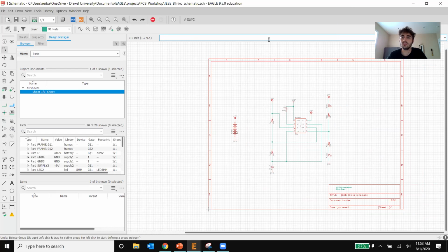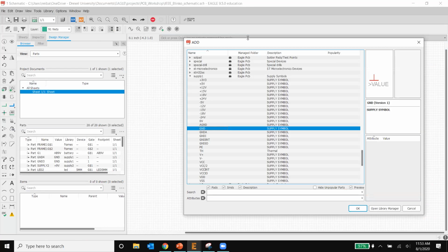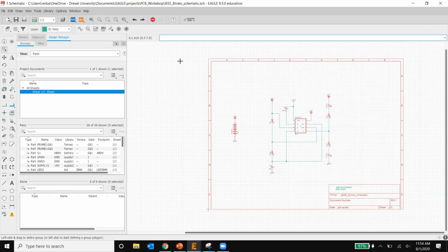Okay, so in this line here, we have the command line. Basically, it's very helpful. Now that I've been using it for some time, it's a bit tedious to hit add part, search, and do all those things every single time. So I can just type add, and it's going to pop up like this, and you use the tab button to go to places. For example, I'm at search, I press tab, go to the other one. Or if you want to move something, you press move, and now you have this command, and you can move things.